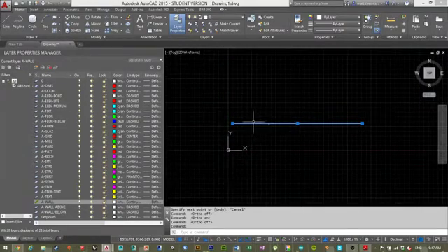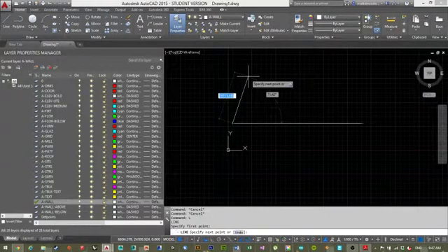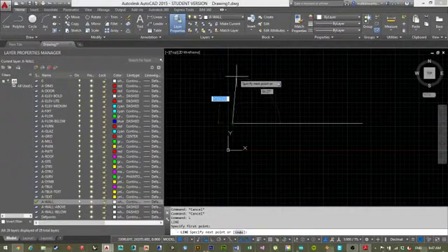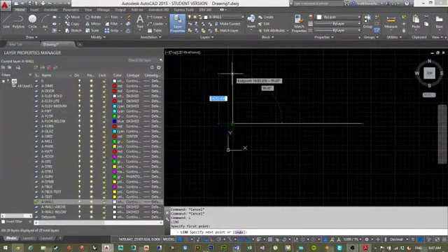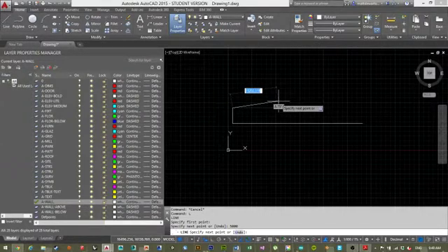Well, you can change. So right now, if I press line like that and I'm drawing a line, it's showing me right now that my line is obviously 16,282. If I just wanted like a 5-meter line, so 5,000, if you just start typing that in, it shows that you're typing it in, and then you see I've drawn a line here that's 5,000 long.